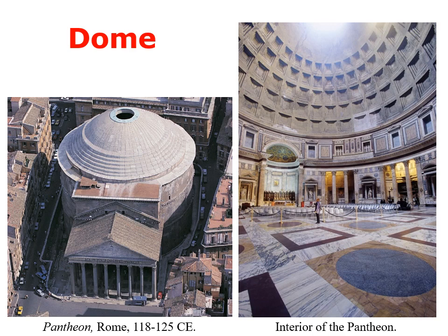So the engineers figured out, okay, if we have this kind of design, we can remove material, making it lighter, but at the same time, it also strengthens it by the pattern that they create. Whereas again, going back to the exterior view, you can see where it stair steps on the top. So that's removing a little bit of material as it goes up, and the opening, the oculus, of course is there to add even more strength. Had they closed it in, then that would actually be the weak part of the dome. So by taking it away, it actually adds strength.